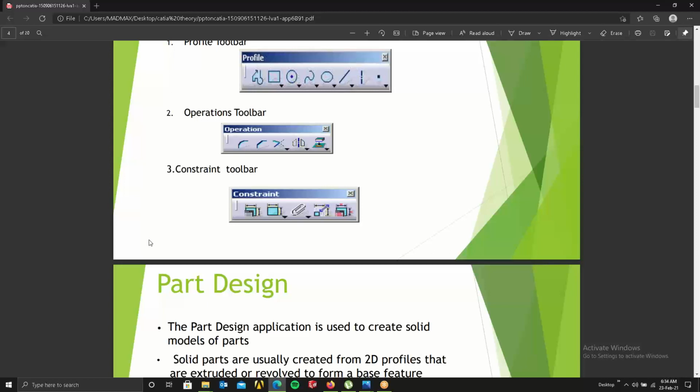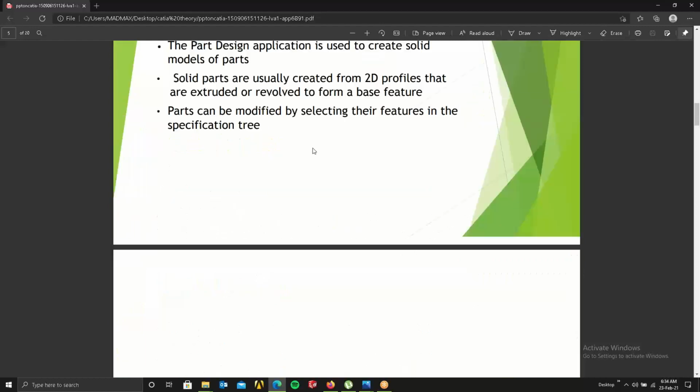And you can even use symmetry command for ease of doing it, so you don't have to complicate your design. So if it's a complex design with similar sides and angles, then what you can do is you can easily use symmetry command. So whatever changes you make in one side, that is reflected on the other side, and you can save both time and your energy. Okay, is that fine?